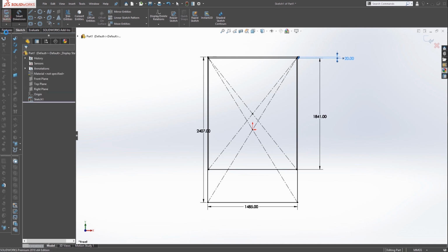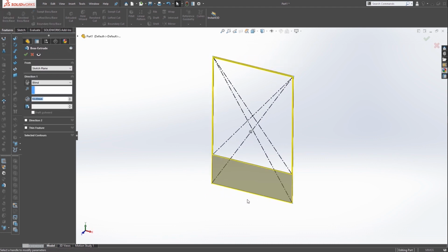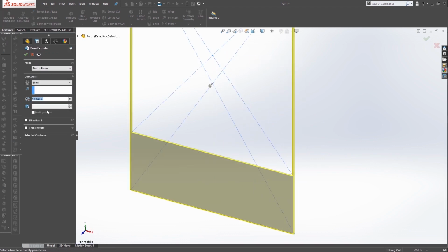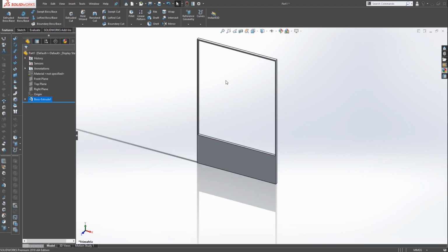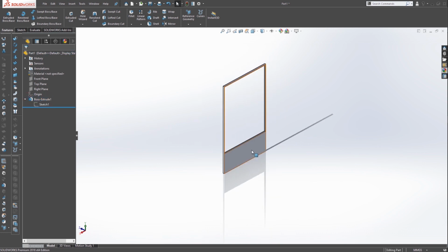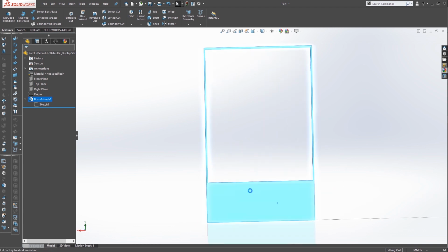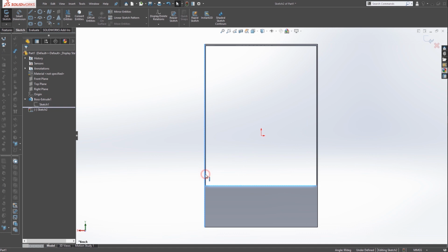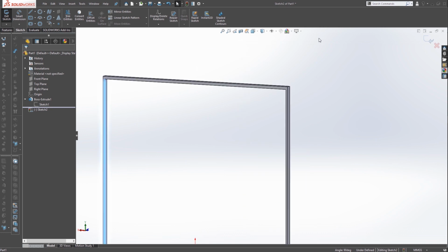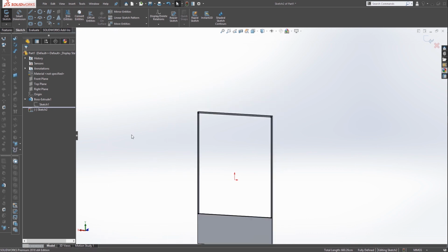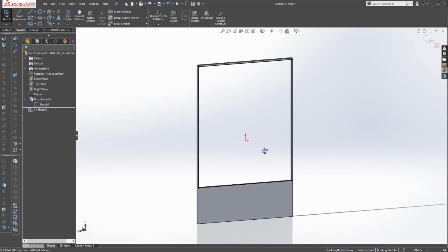Now the next thing is just a simple extrude. The external part will be extruded first, which is 40 mm. Now this logo is actually embedded in the wall. What I will do is go to the back plane, select for sketch, and select all these edges. Okay, edges are selected. Now just press convert entities. It will import the sketch of your selected geometry.